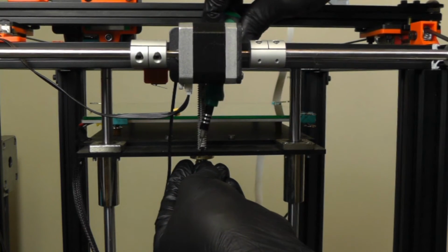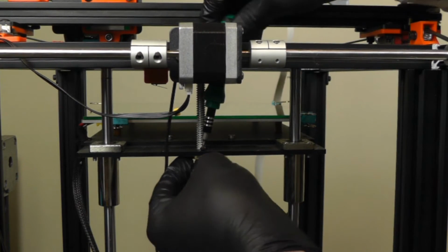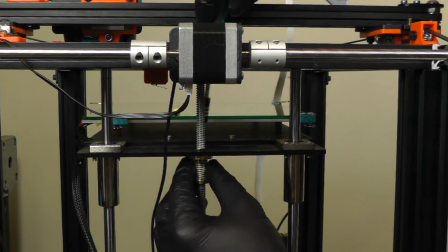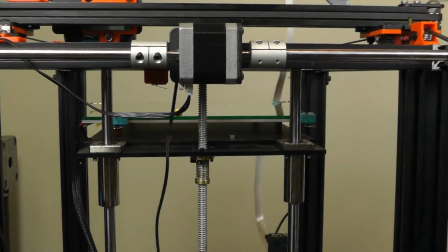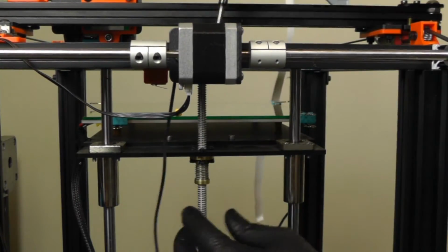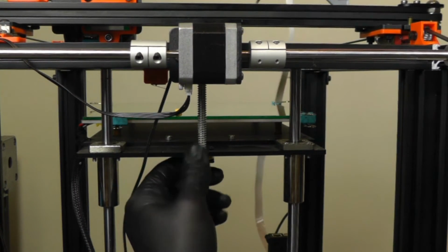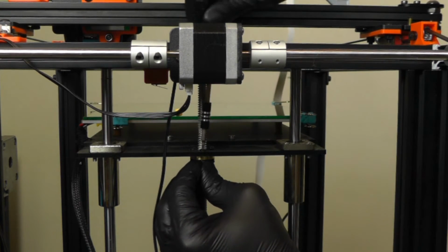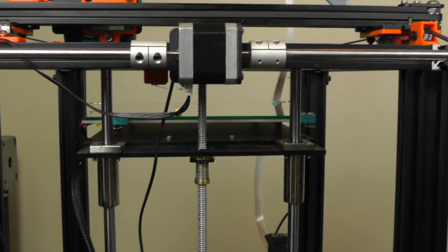Now, we can attach this directly to the plate. And don't tighten this down too far at this point. We need to get all 4 screws in before we do. Now, once all 4 screws are in, this should settle in there and not have much wiggle room, really no place to move it to. Now we can tighten all 4 of these down. There we go. And with the lock washers on there, this shouldn't back out.